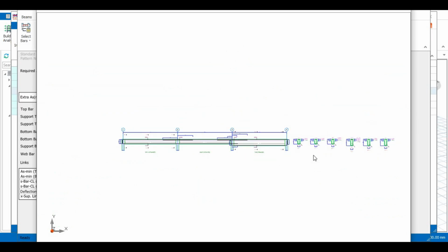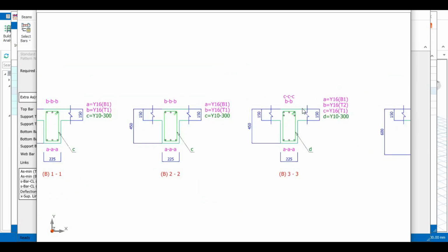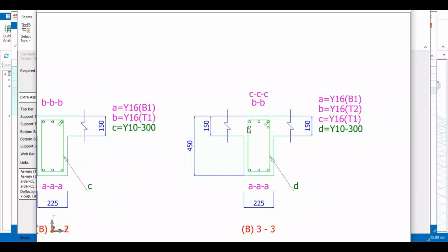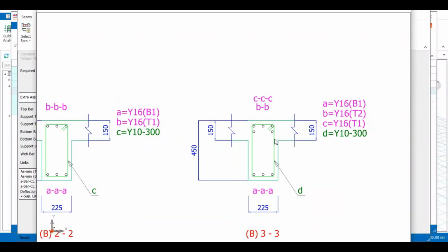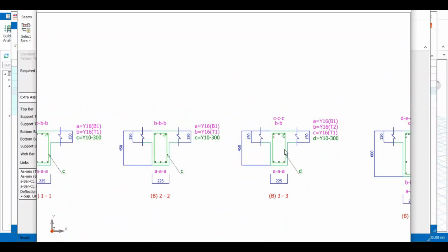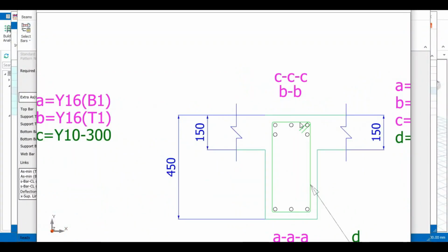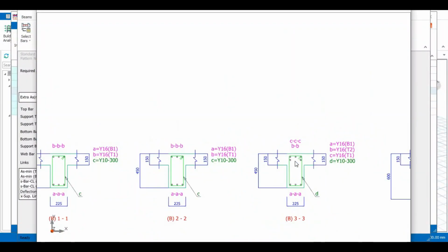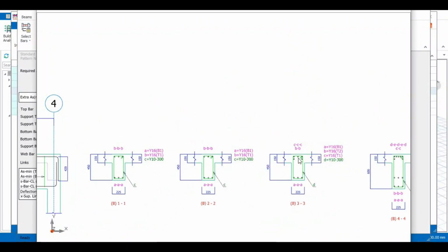As you can see, it's labeled T2, which is top 2. And when you look at it here, you see the illustration of how the reinforcement is going to be installed in your bin. So you have this 1, 2, 3 here. Then after the 1, 2, 3, you install this right under it. So these bars are meant to support these main bars. These are the main top bars, and you have the bottom bars here. So these bars are just going to be supporting these bars, and you have them at the edge as shown.